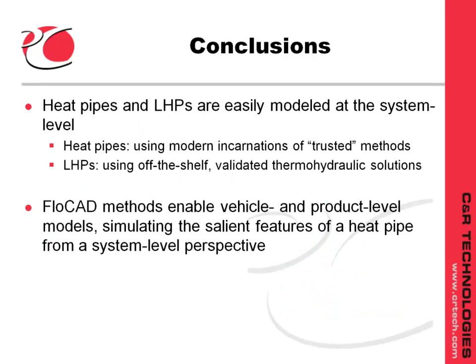Counterflow heat pipes, whether constant or variable conductance, and loop heat pipes can all be modeled using Thermal Desktop's FloCAD module. In the case of heat pipes, the modeling methods are based on time-honored techniques. In the case of LHPs, validated thermohydraulic solutions are applicable. But in both cases, these two-phase devices can be integrated into a system-level model that's perhaps based on a CAD drawing, or that includes finite element meshes, radiation, contact conductance, convection, and so forth.